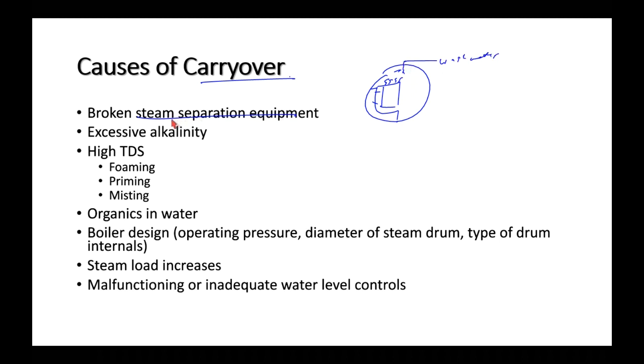And so with all of these steam separation internals, if you've got something that's broken, a cyclone that has come loose and it's not separating properly, or it's corroded and it's not imparting the proper spin, all of these things can cause carryover.